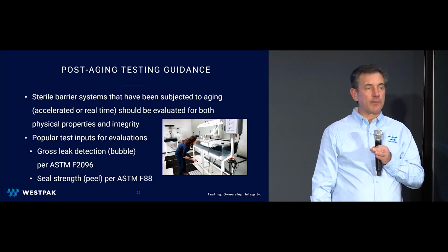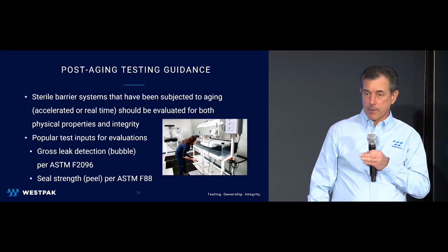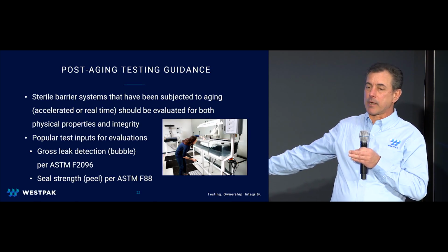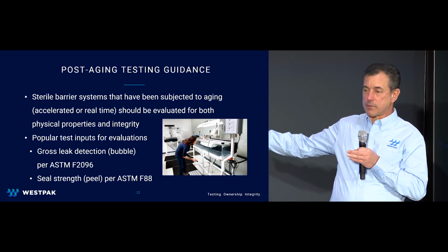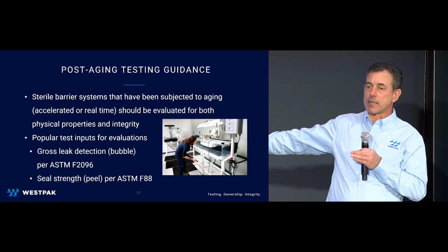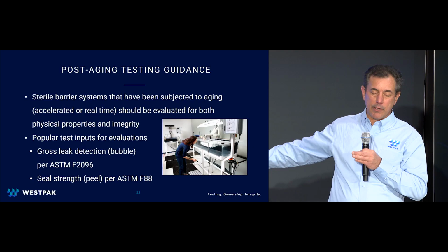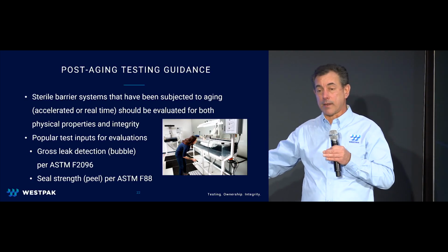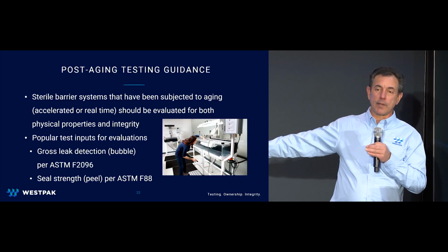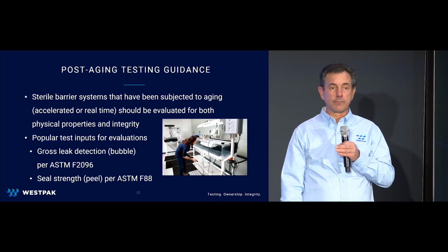Does the humidity level affect the accelerated aging time is the question, and no, it doesn't. The Arrhenius equation only uses the accelerated aging factor and the accelerated aging temperature and the room temperature. It does not take into account any humidity levels. And if we actually go back to the Arrhenius equation, even doing our own research, we find that humidity was not used in the determination of this equation.